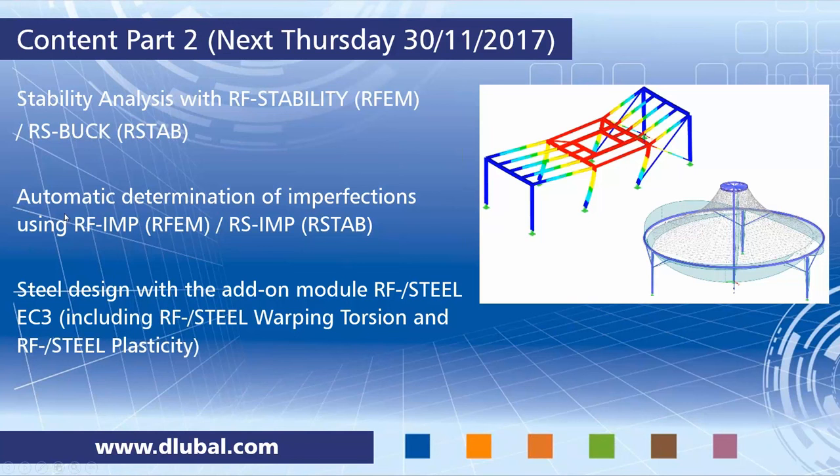And we will manually create imperfections, and we will also automatically determine some imperfections using the add-on modules RF-IMP for RFEM and RSTAB for both. And finally, we are using the module RF-STEEL EC3 or Eurocode 3, including the warping torsion and the plasticity analysis, and we will perform a steel design for our steel platform that we've modeled today.